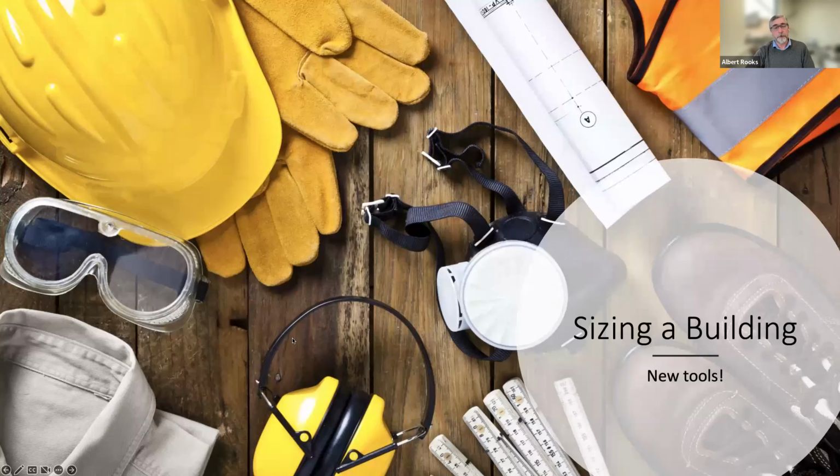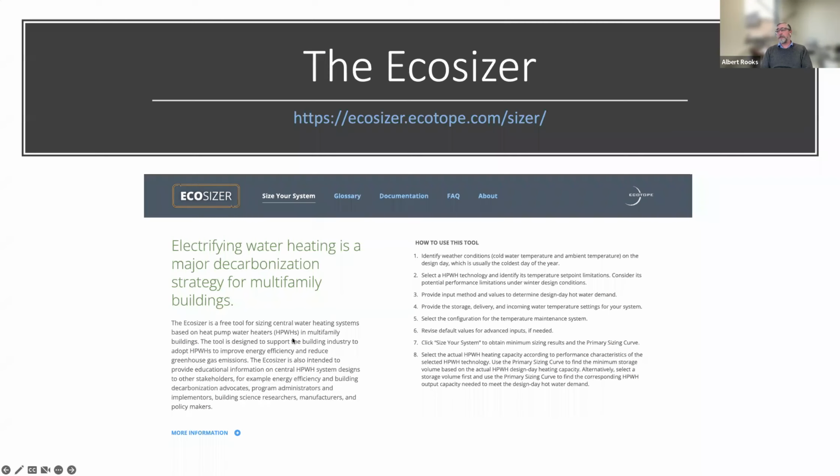So here we go. Here's my redundant slide saying we're going to talk about sizing a plant. And there are new tools. The exciting part of this for me is these new tools. These were developed with utility funding up and down the coast in Canada, Bonneville Power Administration, the whole Advanced Water Heating Initiative. This is one of the problems they wanted to solve: how do we really size a building with heat pumps? Because it's completely different than a boiler. Heat pumps are all about getting the storage right and matching the heat pump capacity to serve that storage based on what the load profile of the building is going to be.